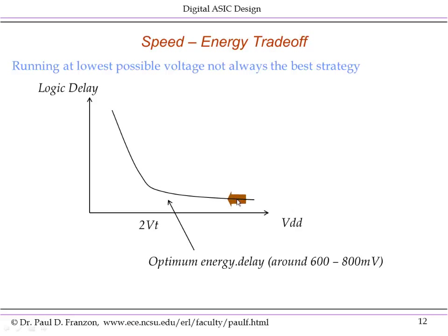It increases slowly up to a point when the voltage VDD is a bit over 2 times the threshold voltage of the transistors. Then it starts increasing very fast. Thus, operating at the lowest possible voltage down here somewhere might not be desirable because your processor will be very slow. And for computing and other applications, that sort of defeats the point.